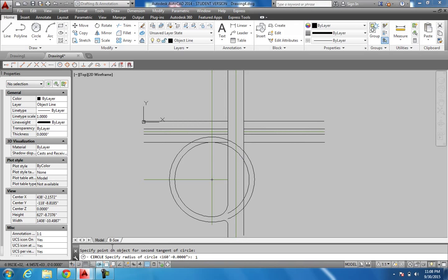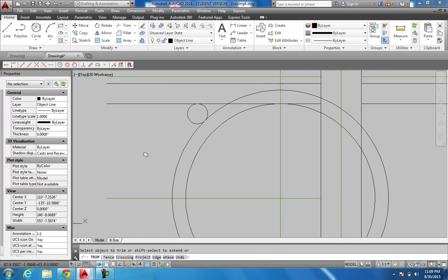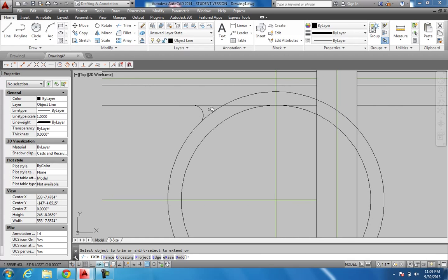It's 15. 15 foot. Click on it, click this and this, and then do a 15 foot. Puts that in there. Then you can just use a trim, right click and enter. Come here and just kind of straighten it all up.